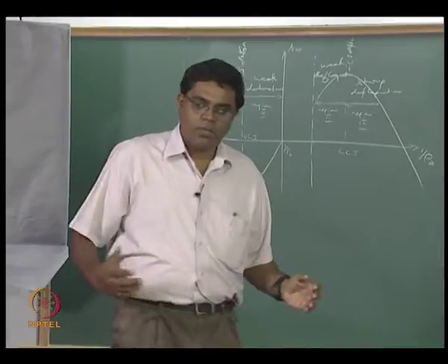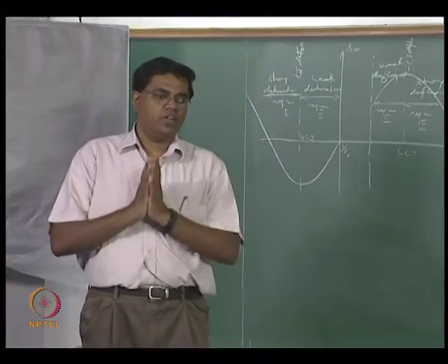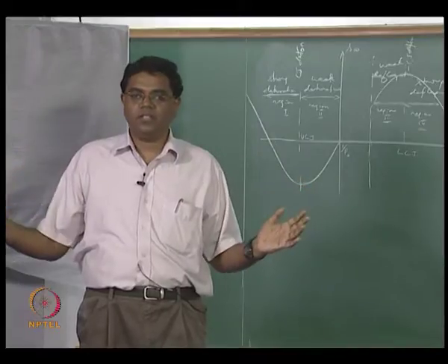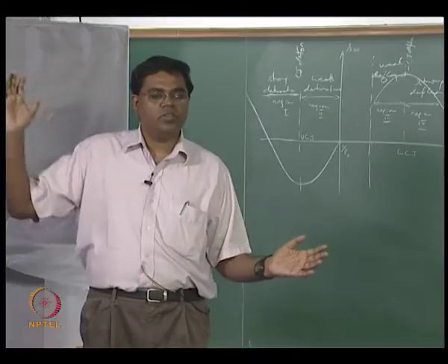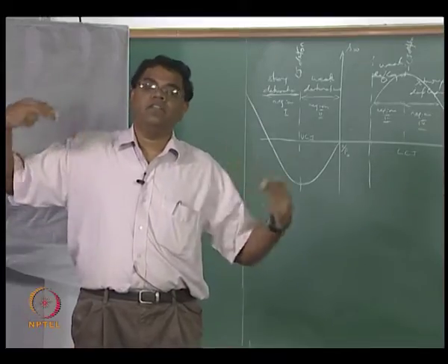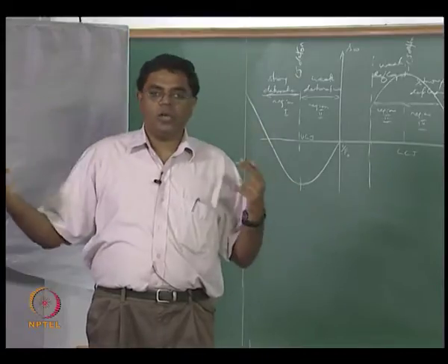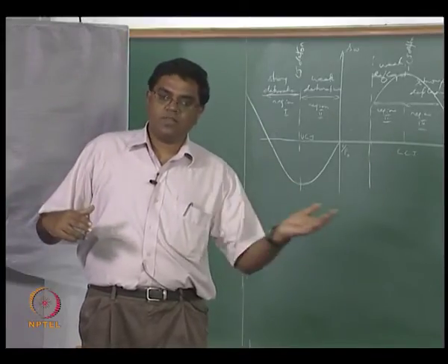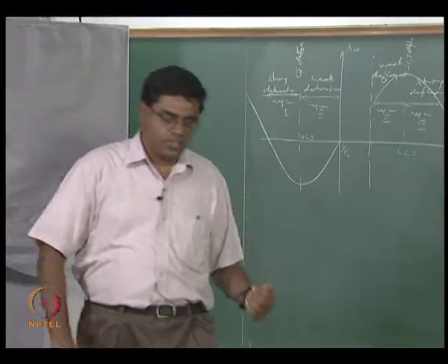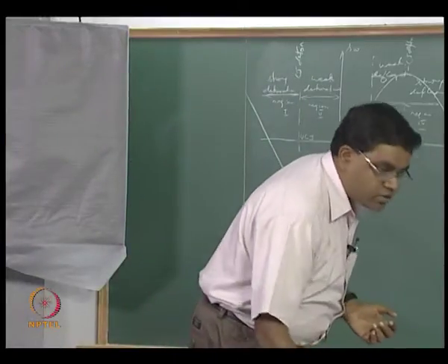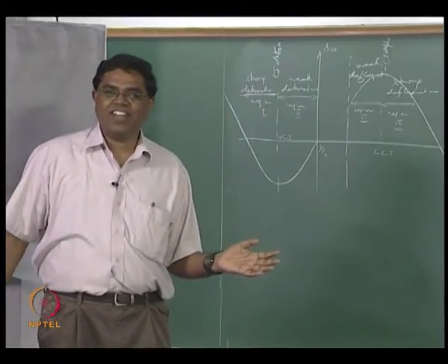And we have now come upon a lot of facts, like we should now be able to say that there are two kinds of waves that are completely apart. One goes as deflagration, subsonic, and another one is detonation and so on. And then we further looked at upstream and downstream conditions to point out that this is subsonic, that's supersonic, then you have strong, weak and all those things, right. But did we ever care about whether this really happens in reality?